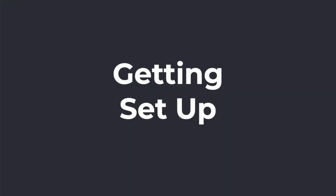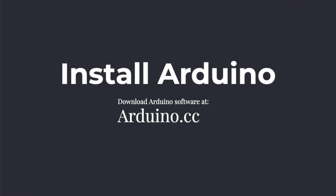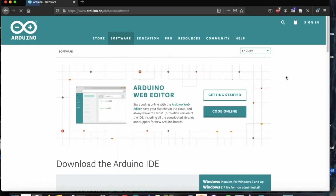Let's get set up. First, you'll want to install the Arduino IDE. To do so, you can go to arduino.cc, and under Software, you'll see a download link. You'll want to download the correct version, whether you're on Mac or PC. Once you're at the Arduino homepage, you'll want to go to Software, and then go down to Downloads. You'll also see that there's an Arduino web editor, but we're going to download the Arduino IDE.